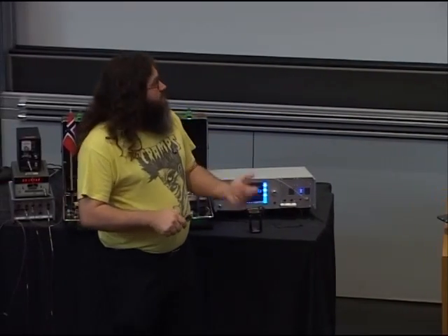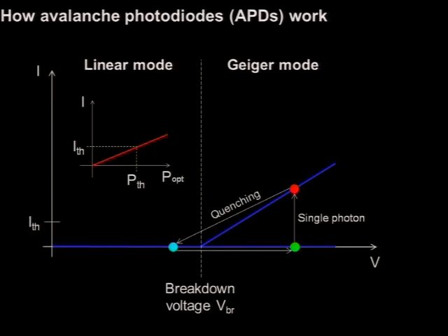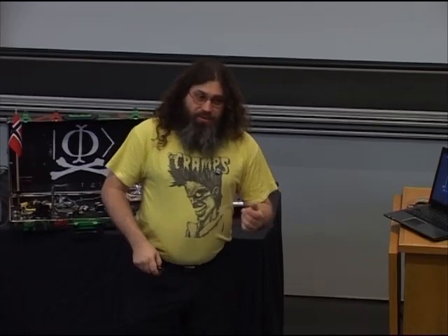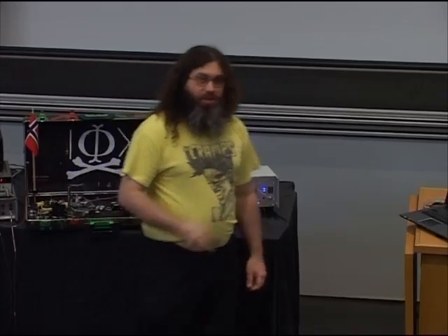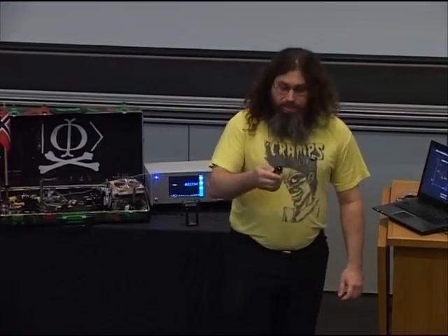When the voltage at the APD is below the breakdown voltage, it is still a photodiode. It doesn't really see single photons, but it still has classical photosensitivity. So if someone applies bright illumination to the APD biased below breakdown, it will generate photocurrent, which might look exactly like this avalanche current. And now the detector can register a click with a classical threshold on the power of the input illumination. If the eavesdropper has access to single photon detectors in such a linear regime, the eavesdropper can fully control the detectors with a classical threshold and break the security completely.